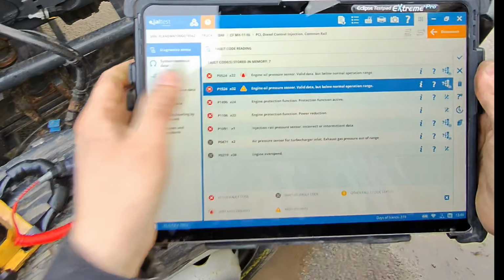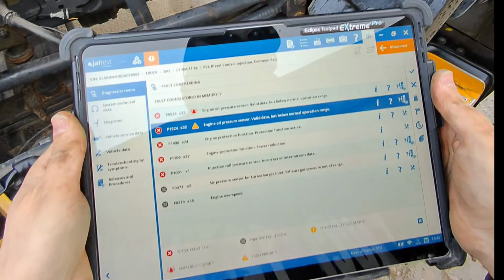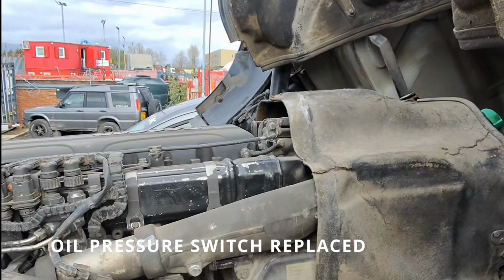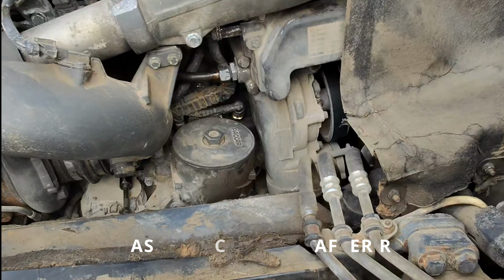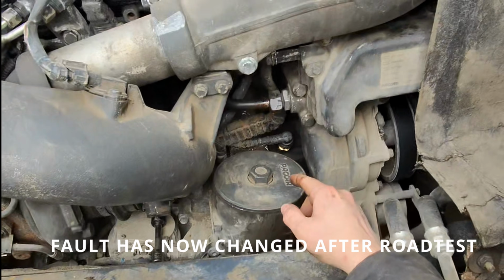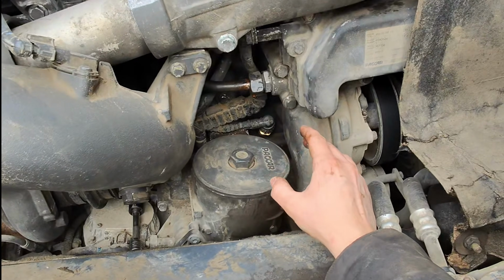I think looking at the fault codes, we're going to need a new switch. The truck keeps having yellow and red oil pressure faults on the dash. It did have a consistent red oil pressure fault, which I then changed the oil pressure switch, which then gave us an actual oil pressure reading on Jaltest. So now we're actually getting oil pressure.